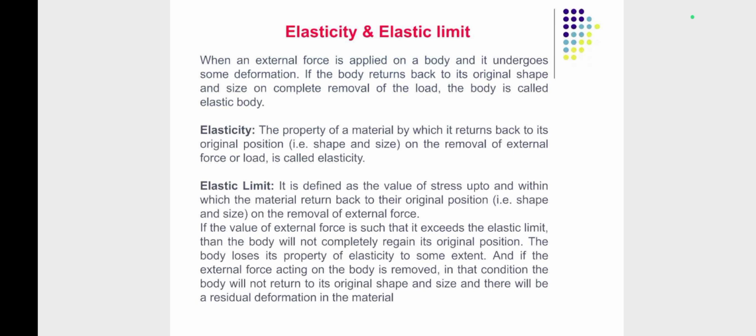The elastic limit is that value of stress up to and within which the material returns back to its original position, that is its shape and size, on the removal of external force. If the value of external force is such that it exceeds the elastic limit, then the body will not completely regain its original position. It means that elastic limit is the extreme limit of the body where it regains its original position. After the elastic limit, that body falls into the plastic region.